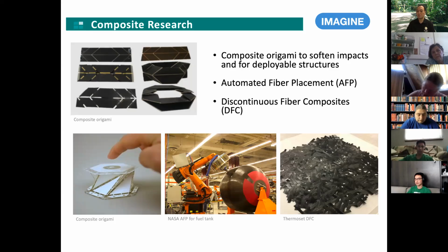And then what I'm working on is discontinuous fiber composite, which has a lot of advantages over continuous fiber because of its manufacturability. With continuous fiber, because it's all one long strand, a lot of times it's hard to make complicated geometries. Since this is all separate platelets, it's a lot more bendable and flexible to make these complicated geometries.